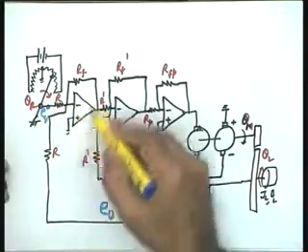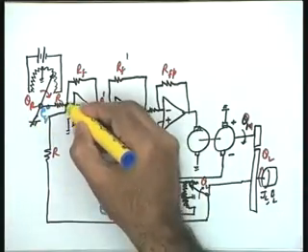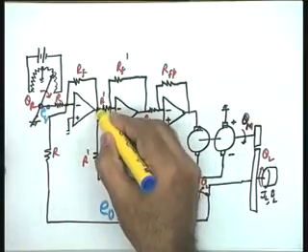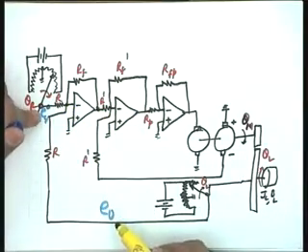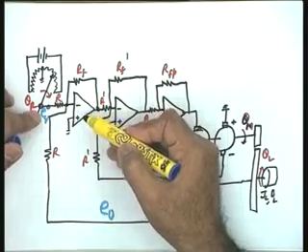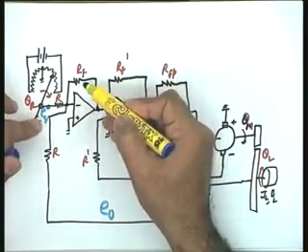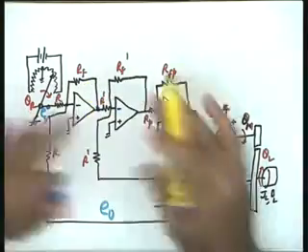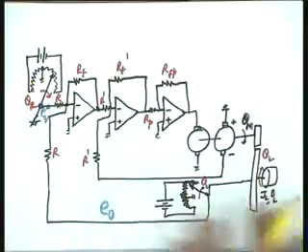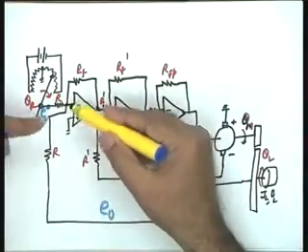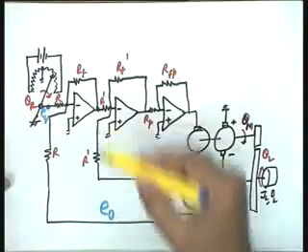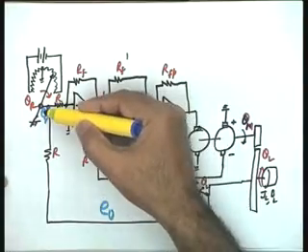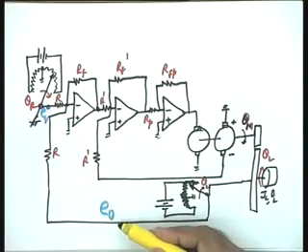Now look at this op amp circuit. This particular op-amp is giving you a voltage which is proportional to ER minus E naught. So it is acting as a differential amplifier with gain minus RF by R. I will give you the block diagram, but first let me scan it all through. The gain is minus RF by R and it is a differential amplifier because it is giving you a signal ER minus E naught.